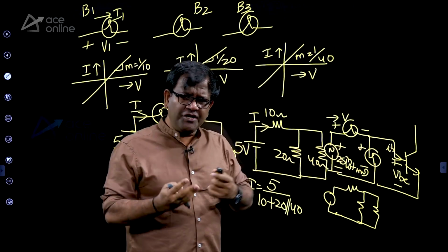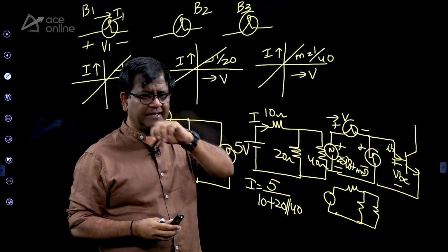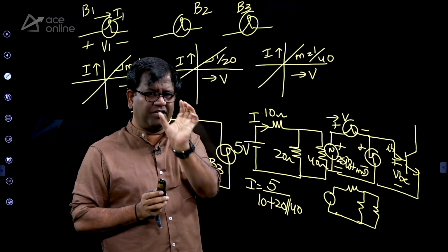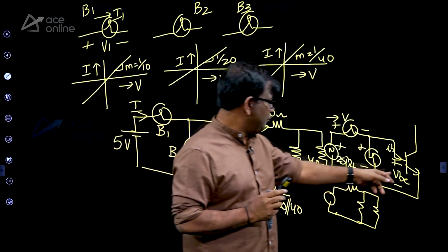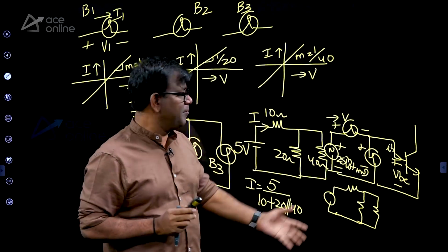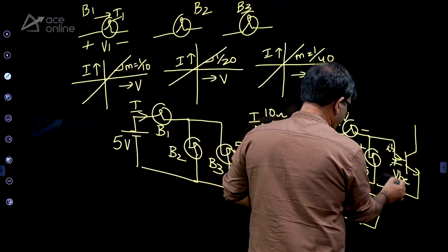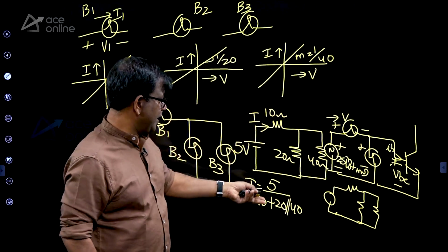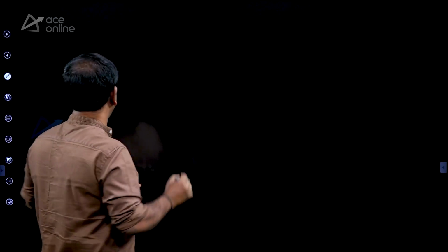So analog engineers, they don't care if it's a bulb or a transistor or a diode. They only talk about, okay, there's a V and there's an I and there's a characteristic. So if you know the relationship between VB by IB, which I will give you, right? The small signal model gives you some R pi here. So you can replace it and you can solve the problem. Okay.